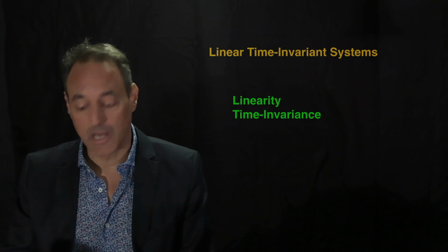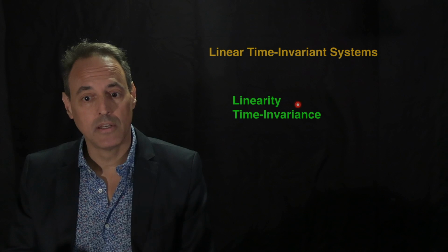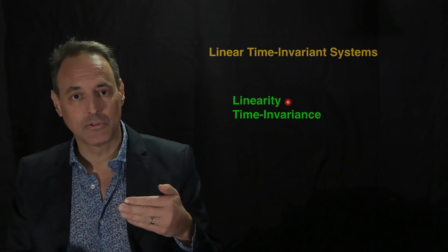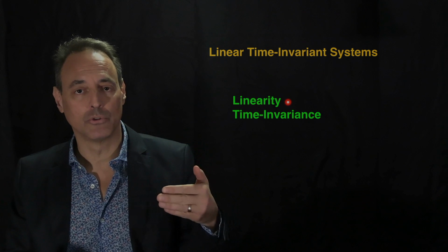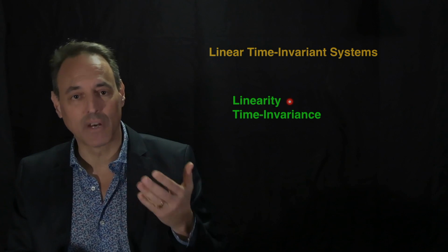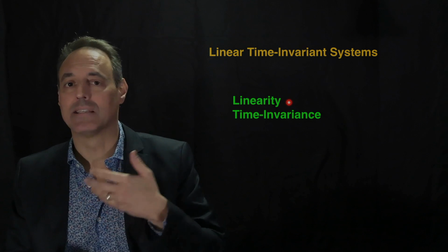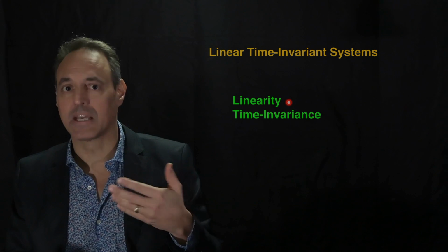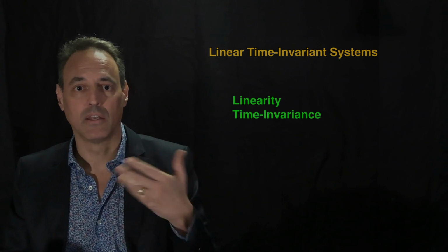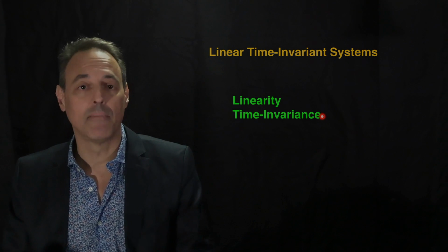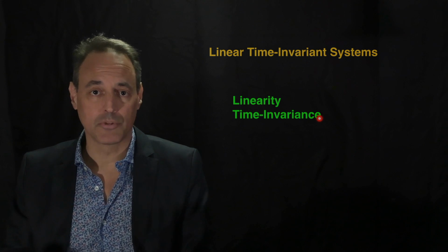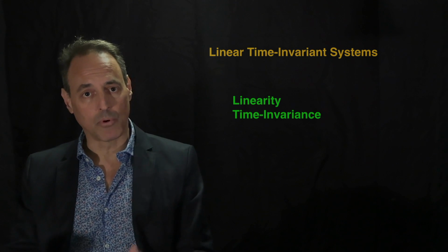Again, everything's going to rely on these two properties here, linearity and time invariance. Linearity says I can take solutions, add them together, it's still a solution. So when we integrate over our solution space, we are actually integrating all these solutions together, and since I can add solutions and it's still a solution, that summation, or that integration, will work for us. The time invariance says that no matter where I kick the system, the response is the same. And that's a really important property as well.